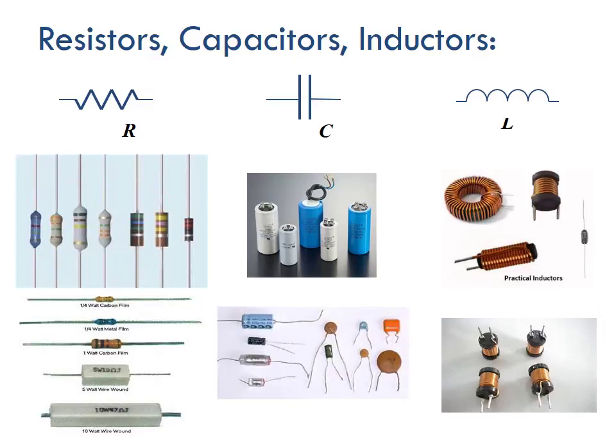Capacitors in the middle, we've got a whole bunch of different types of capacitors, electrolytic capacitors, ceramic capacitors. Electrolytic capacitors generally have a positive and a negative direction. Ceramic capacitors generally are non-directional, so it doesn't really matter. Resistors, to go back to that, are non-directional. It doesn't matter which order you put them in. So capacitors we've introduced previously. Please go back to the previous slide or look on YouTube or whatnot to be able to familiarize yourself with these. And finally, on the right, we have L, which stands for the symbol we use for inductors.